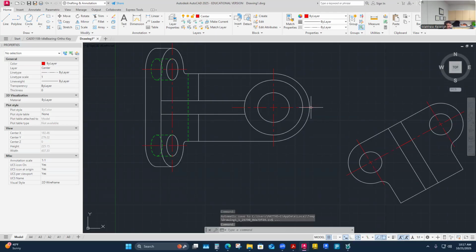The truly tangent point of this, the point of tangency to the real y-axis line here, would be a very small surface, right? So pulling dimensions left to right, or right to left, from that is probably not the best. And pulling from here, left to right off this little edge, this isn't a surface, this is an edge.